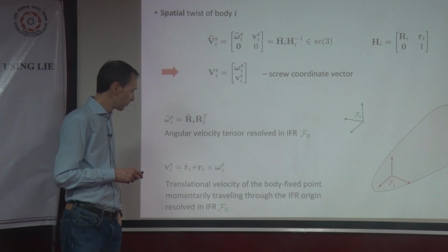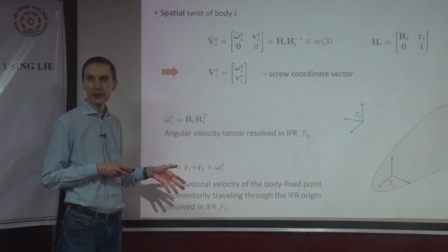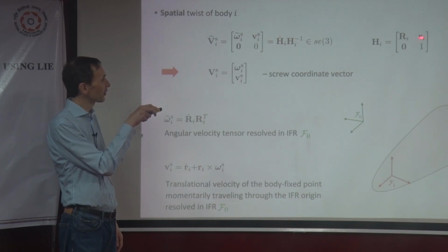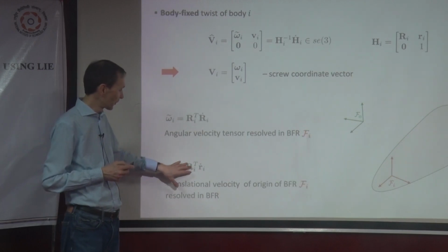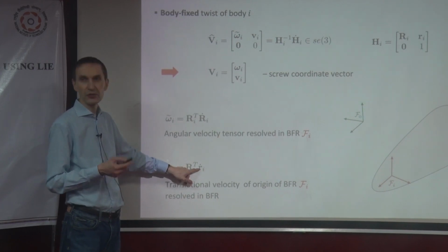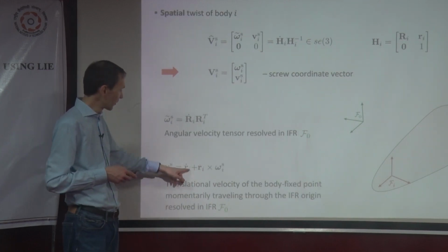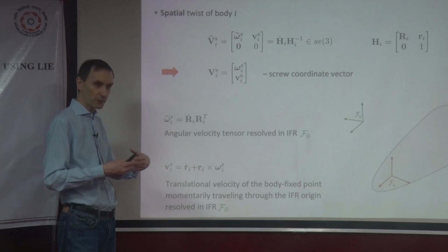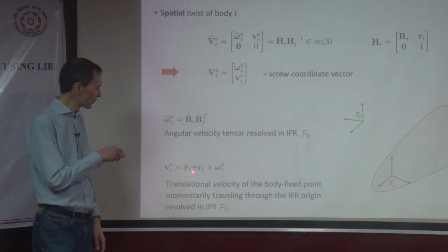What is more mind-boggling, or a bit puzzling maybe, is the linear velocity. Because it's the same. Just do the computation, plug this in, and what you get is this, right? So remember the obvious notion of linear velocity: I have the r dot, which is of course the velocity, I transform it to the body frame, then we have this. What you get here is different. Of course, there's no rotation matrix involved in this because we express everything in the space fixed frame. But then the question is, what is actually the velocity? Of which point is this the velocity?